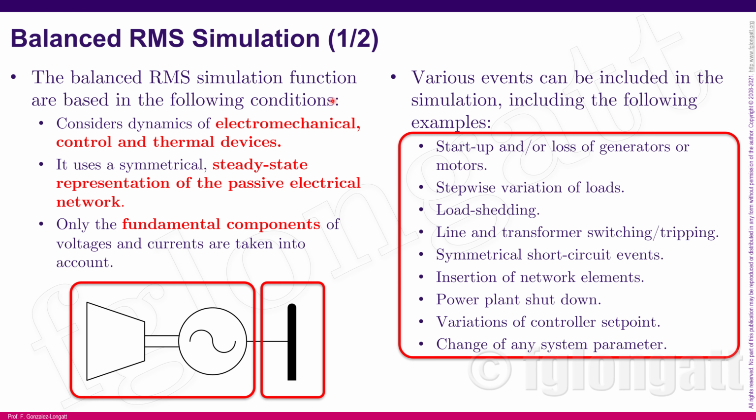The first thing that you need to know is that they are very good for including the phenomena related to electromechanical processes, I mean the behavior of the synchronous machine, but also other kinds of controllers and thermal devices. What I'm telling you is that this balanced RMS simulation can be used to include the behavior, for instance, of the governors, the AVR, and some other devices that are relevant for this time scale, okay?